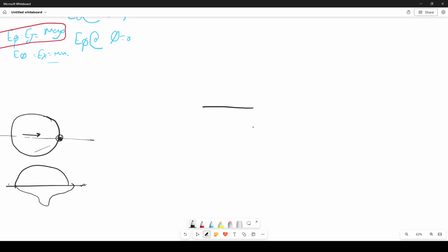if we have the patch here and we have the slot, so it couples, this is the pattern, right? And this is the coupling on the slot. So it does not interfere much with the antenna, does not introduce much asymmetry, means that it just couples with it radiation wise. The antenna itself is not bothered, in comparison with coaxial feeding, where I go like this and then I feed like this.